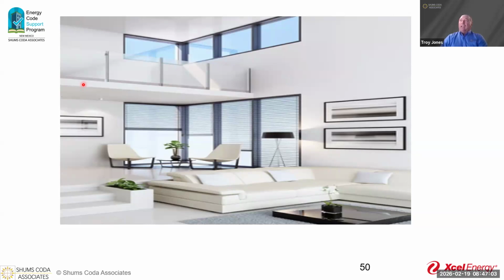Do they require lighting controls for our lights in here? We're also going to say that they have 450 watts of energy going on inside of 5 feet of the window. We have some very high can lights going on in here and also up here. Do we need to have daylight responsive controls on this?